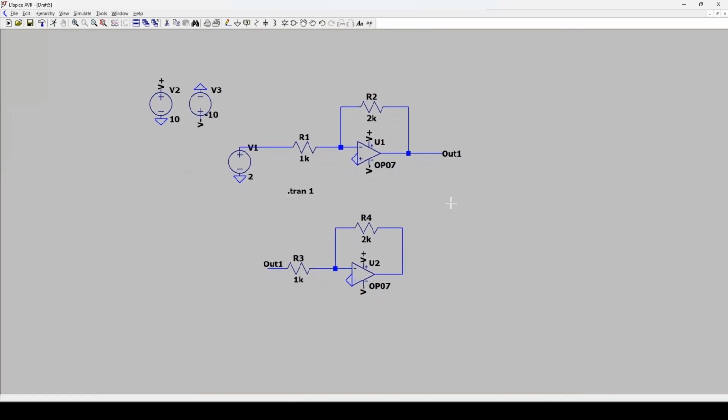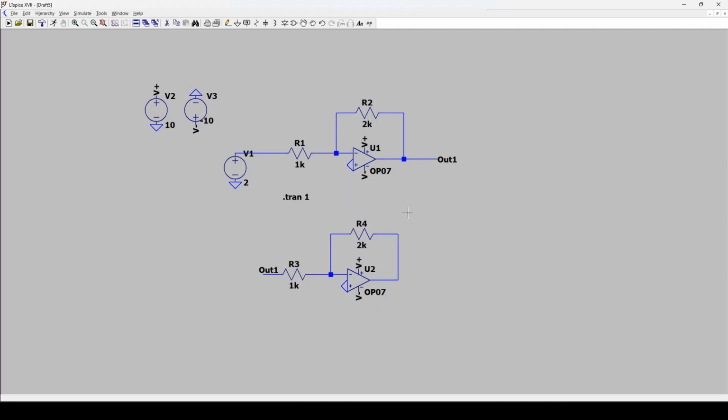So I don't recommend using it for everything. I would recommend it for separating different parts of your circuit, or especially if you're using shared power supplies, using that rather than using wires to connect them, as it's an easier process. And as we start to build up our summing amplifier into something that's a bit more complex with a few more components, you'll find that using nets and labels becomes a pretty handy tool to have.